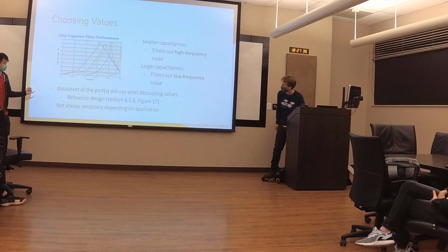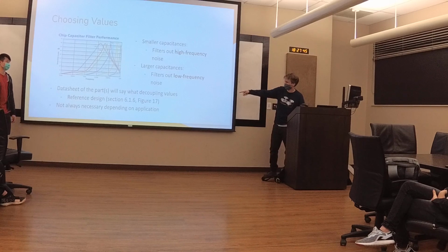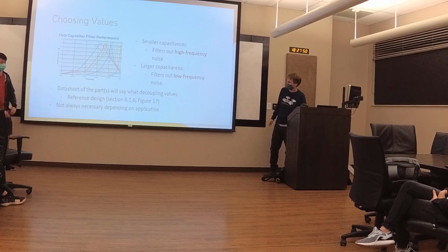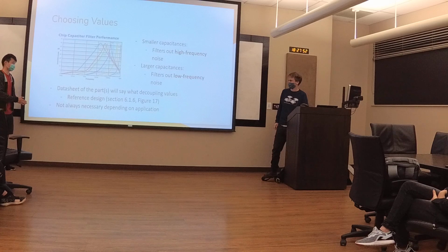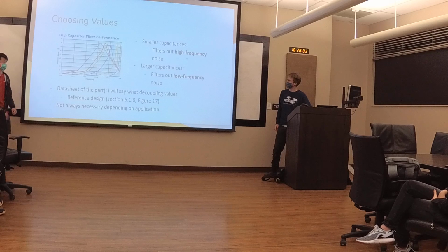I'm not sure what this is. Is this for DMC? I believe that this was a reference to the microcontroller, or it might have been a reference to the voltage regulator that I was going to demo at the end. I'm not quite certain. Basically, the idea is you're going to be searching through the data sheet. The data sheets are very long, but there are always certain sections that are way more important than the other ones, and that's what is relevant to us. You will find out what values to use, so you won't have to guess.